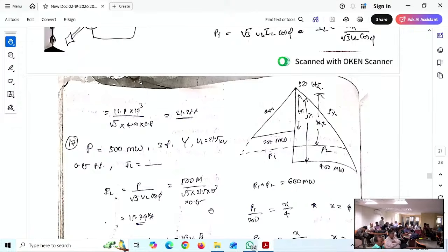If I keep 200 as maximum, share 600. Now that is not 600, maximum load is not 600, because if you keep 600, this is giving 230, overload. I do not want overload, but maximum load. So if I am fixing this at 200, this is coming under 400, 200 is lesser than this, so this can share more. One power I am fixing. Machine P1 share under the maximum load sharing operation is given 200, that is fixed. P2 share must be calculated, and what maximum value this set can deliver, that we should calculate.